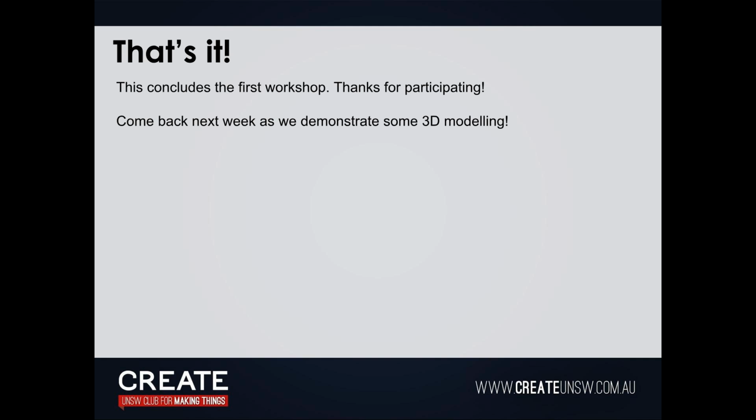Assume we'll make a 3-finger joint, so roughly each joint is about 20 millimeters or so. That's done. Now we'll edit the top face of that. Oh, not edit profile sketch, sorry about that.